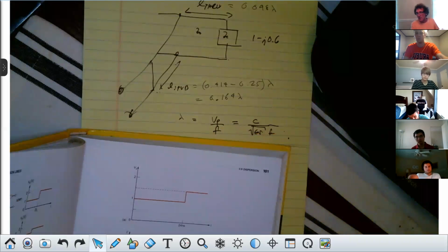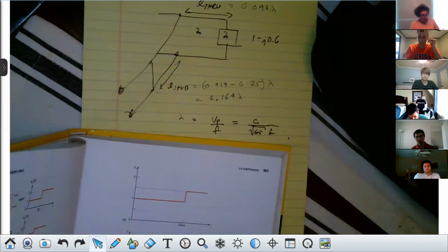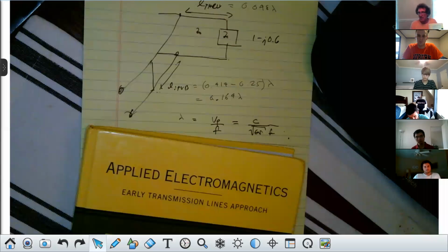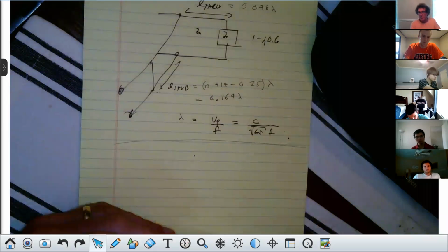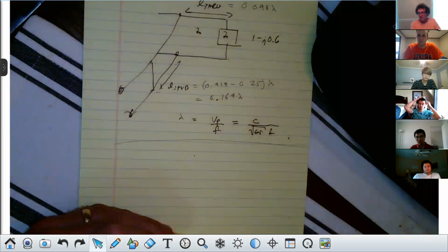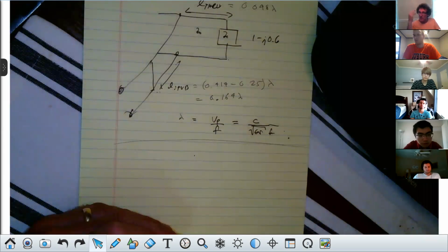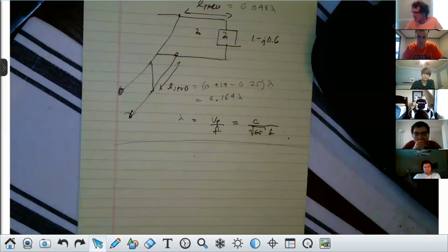Now, I'm not going to give you any homework, but make sure you understand impedance matching well. And any questions you have on Monday, we'll take up on impedance matching. You guys pretty good with this now, with the impedance matching? Okay. And go through it with your mind. If you're using an inductor or capacitor in series or parallel, 4 possible places, right? Think about where you'd locate them if you wanted to minimize the length from the load, say. Things like that. And then if you're going to do the same thing with stubs, where do you locate the stub and why? If you want a minimal distance on the stub. That's it in a nutshell.